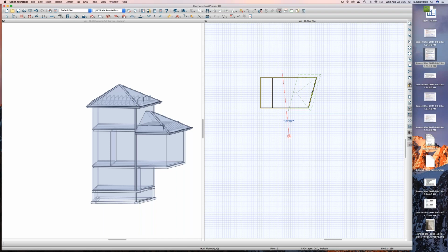Well, it would be by option, meaning the option would be to either have it disconnected totally or connected at the baseline as opposed to anything else. But we can do that now. Can you connect it to the baseline? Yeah, you can use a roof baseline polyline, which then controls the roof completely independently of the rooms.